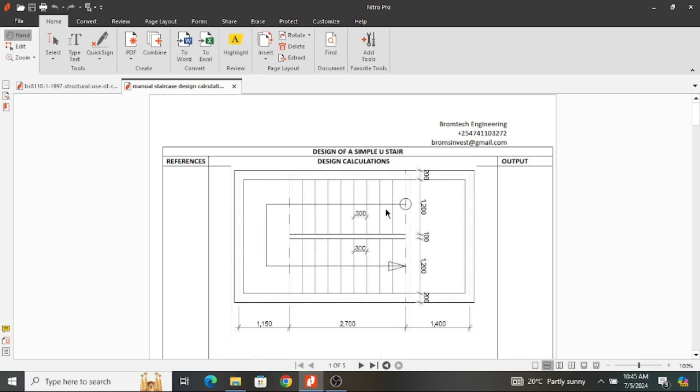one axis. And you can see the width of my staircase is 1200 mm wide, and that is the width of my flight. And the other flight, it's also the same. And once you look at these treads, they look exactly the same. Therefore, they are also the same in number. And the distance between one flight to the next, just that void that we normally have at the center, is 100 mm wide.